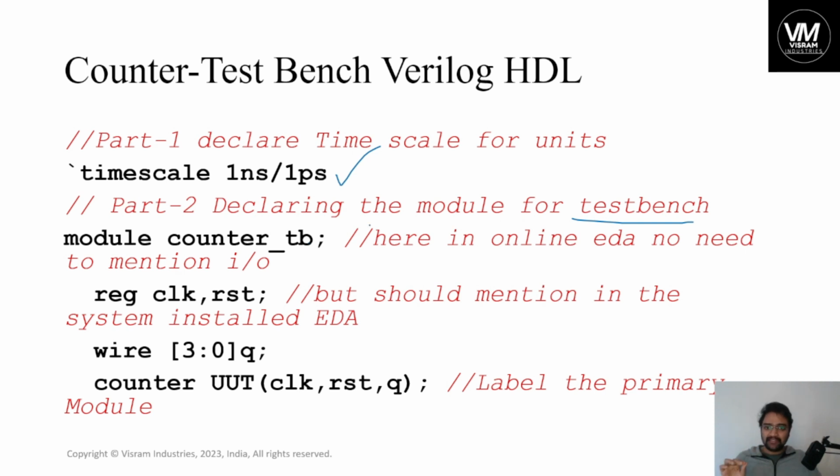So again, guys, remember, some of you are asking about this test bench VHDL: we ignore this on the FPGA architecture. We don't want this test bench there. We are writing this test bench to check the hardware description language code in text format, whether it is working, using simulation. That simulation we have done using timestamps, so we can check it.